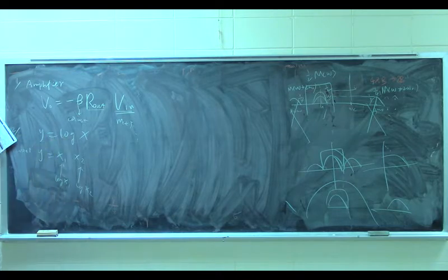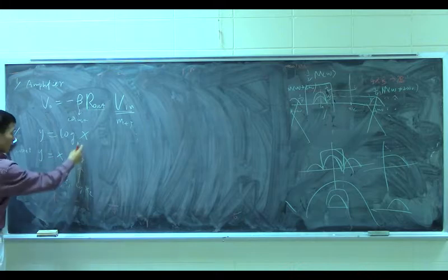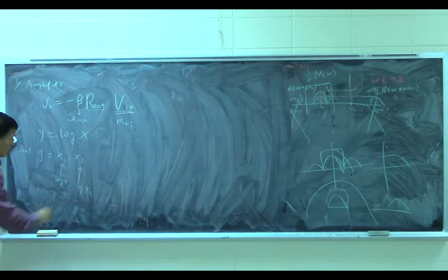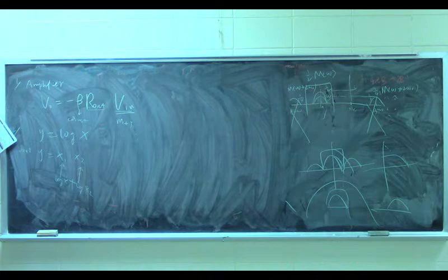You use this logarithmic amplifier. Then for this one, I also take the log. Then we add these together. Use the adder, not multiply, because we want to implement the multiplier.